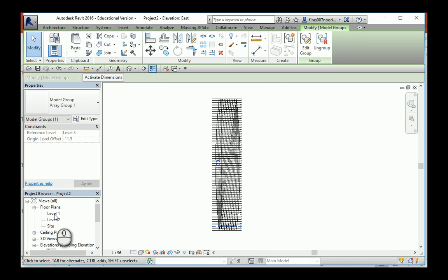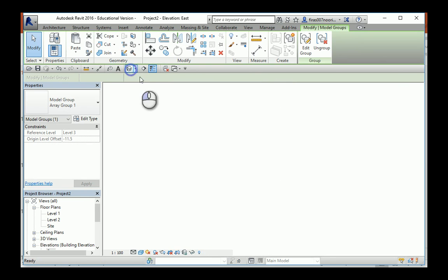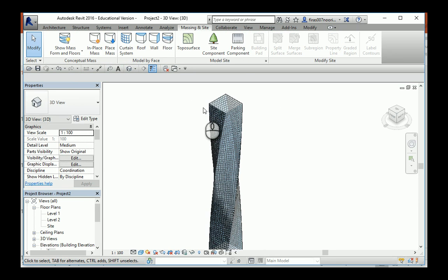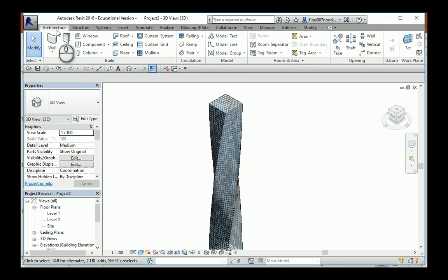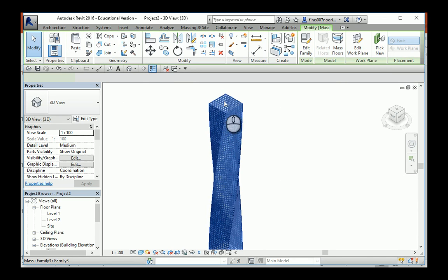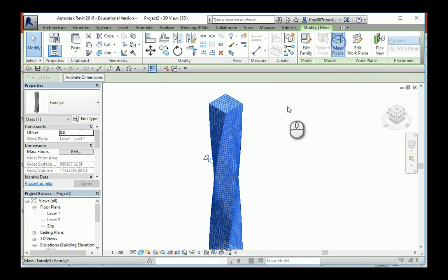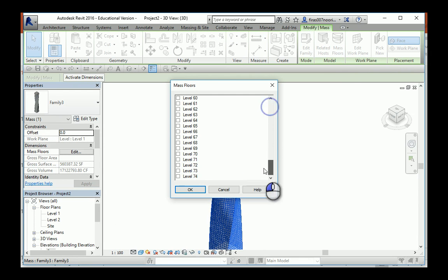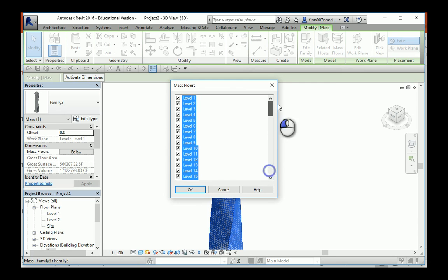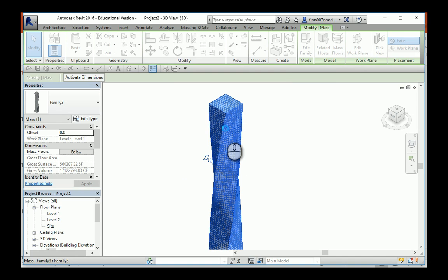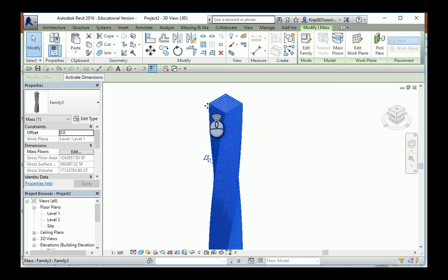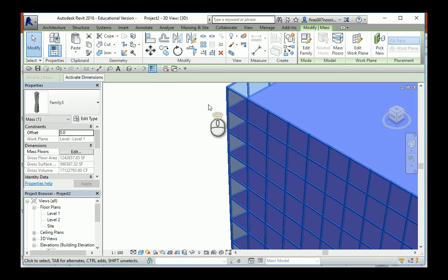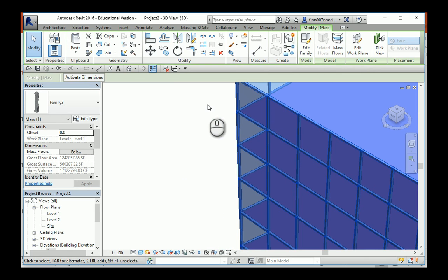That's going to be really long here, but before, let's create our slabs. So again, you can go here. First I'm going to select the mass itself and mass floors here. First select the first one, then scroll down with shift, select the last one, and then I'm going to tick here. Don't be brave and select them one by one. That's so unfair for your fingers. So just select them all at once, as I did. You can notice it might take a couple of seconds for Revit to create those conceptual floors.